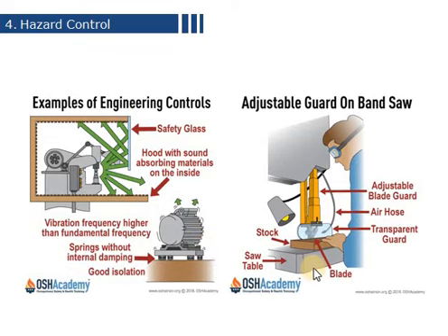Here on the other side, you can see that this blade might hurt this worker's fingers, because he has to touch or keep his hand on the table. So when placing this transparent guard, he will protect his fingers, and since it's transparent, he will have a good visual while working on this device.